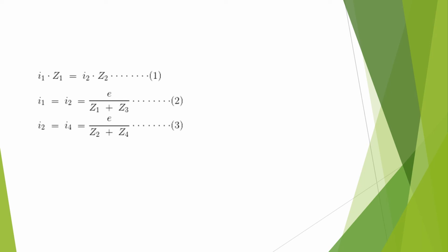So the main points to be concluded are we get two balance equations that are obtained by equating real and imaginary parts. This means for an AC bridge both the relations, that is magnitude and phase, must be satisfied at the same time. Both the equations are said to be independent if and only if both equations contain a single variable element. This variable can be inductor or resistor.